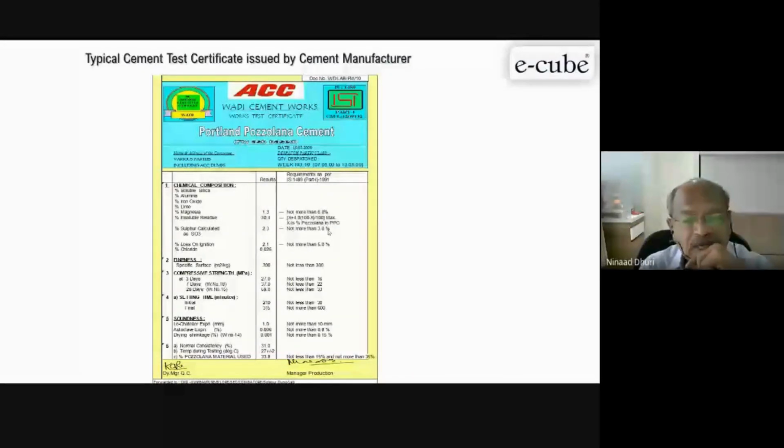Now this week number starts from January 1 and goes up to 52 weeks. So when we look at the bags, we will understand when your cement was produced. Here, the week number is given with its range, the week dates. Another mandatory item is your IS code number. The IS code number is also on the bag, and on the certificate.